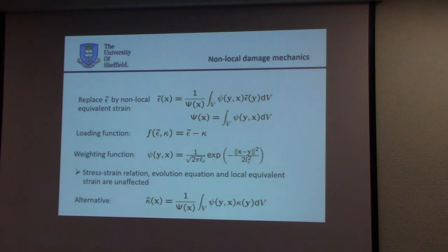You can cut it off at some point, but even then, they increase the bandedness of your stiffness matrix enormously, because there is an influence between this point and this point. So that's not nice. Even worse, even if you manage to keep a damage formulation that is symmetric, this will destroy it. So an integral formulation gives rise to very nasty stiffness formulations which are not symmetric.